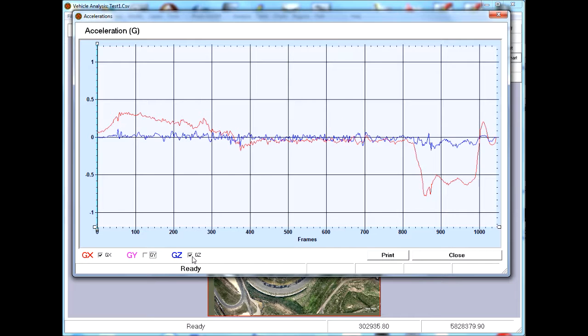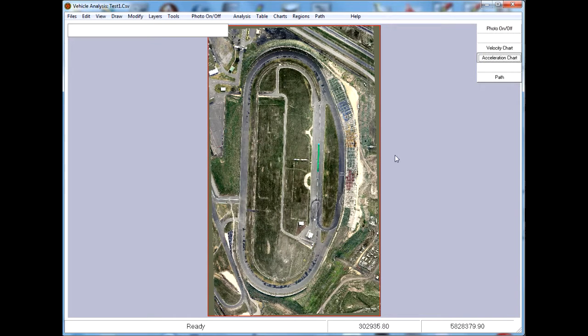If we cut the G1 and GZ out of the screen, we can see our acceleration at the beginning of the chart, and then going down to constant speed, just varying the speed, and then we have our braking peak. And at this point, the braking peak is 0.779 G. And as with a lot of these, there's a peak value, and then the braking continues, but at a slightly lower level until the vehicle is stationary. So that's how we cut isolated sections out of the larger recorded data.